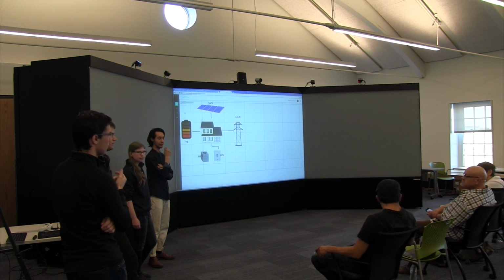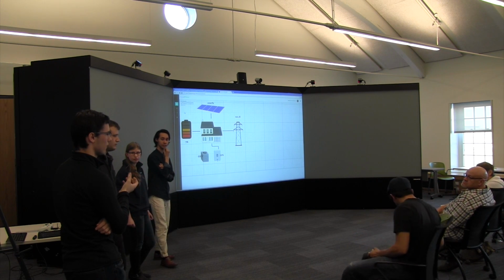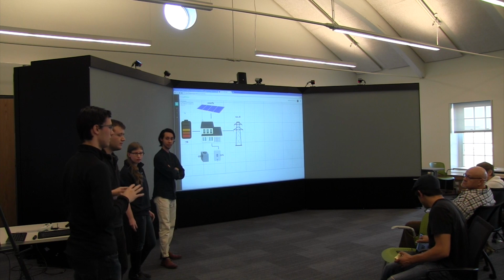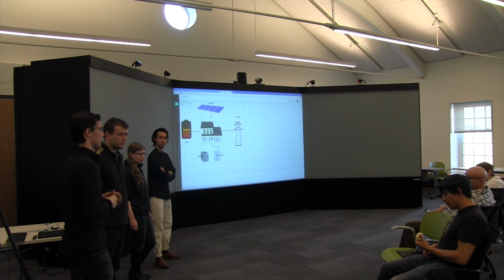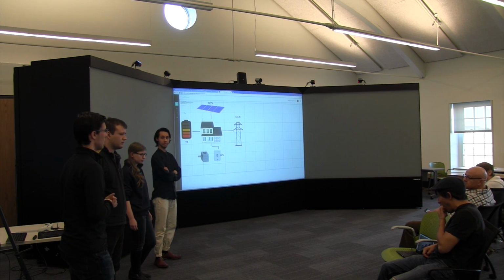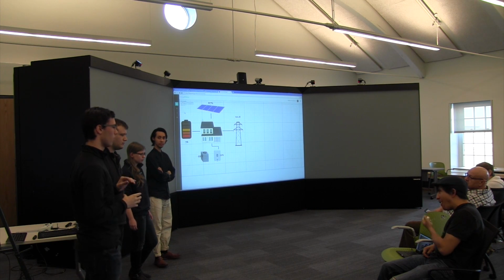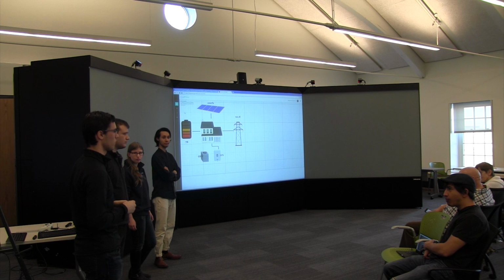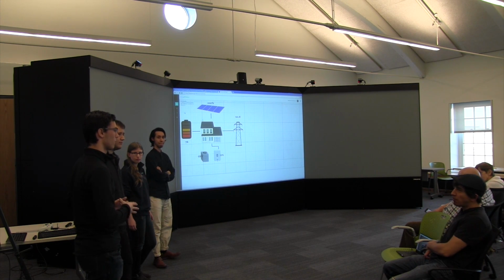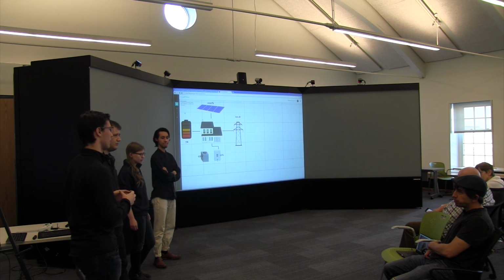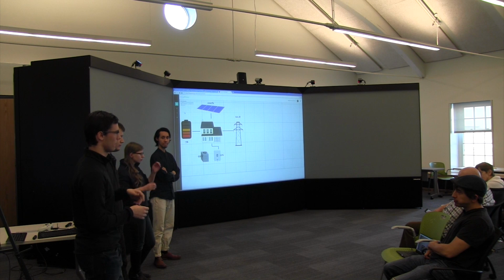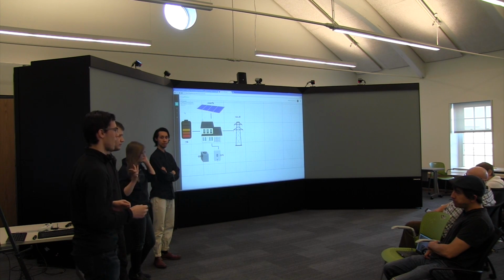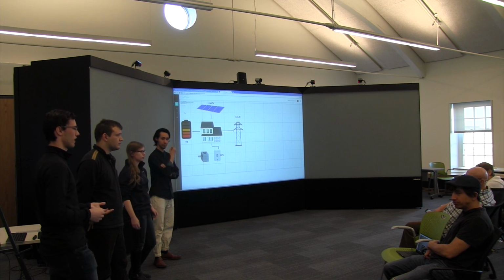Based on our estimates, we used a Tesla wall charger as the basis for the battery cell. That was around 3.3 kilowatts of power that it can ramp down and up, which is what you get paid for that frequency response. Then it has a 10 kilowatt-hour battery that you're able to charge and discharge.